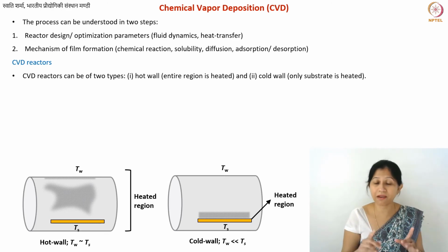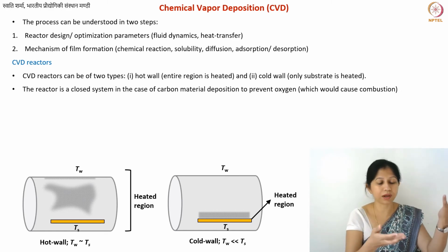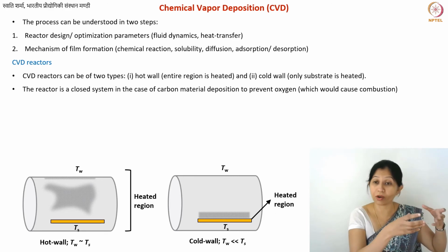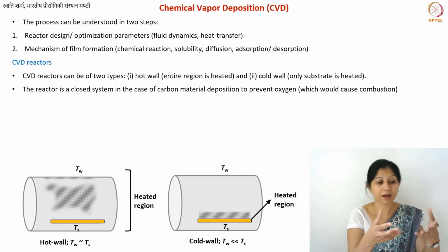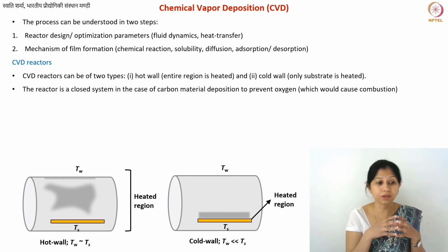So one more very, very important parameter inside all the CVD chambers: you must have a laminar flow and not a turbulent flow, because you want to get a film deposition, right? With turbulent flow, at some locations you will have a lot of deposition, then some locations will not have any deposition, and so on. So you definitely do not want a turbulent flow. So what you need to do is have a laminar flow inside your system.